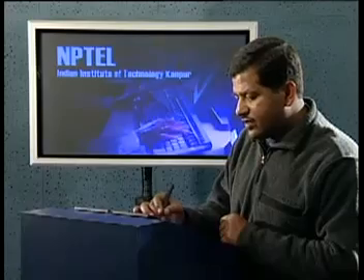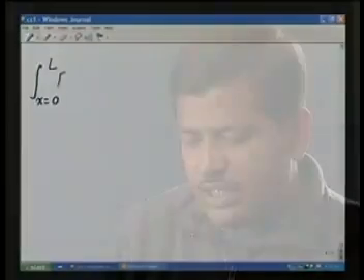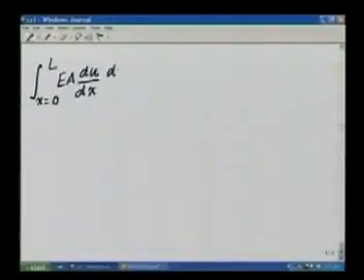So if we have that formulation, we have integral x equal to 0 to L EA du dx d delta u dx dx. This will be equal to, by our definition of the variation, keeping EA as a given constant. We cannot vary EA because this is something that is supplied to us.